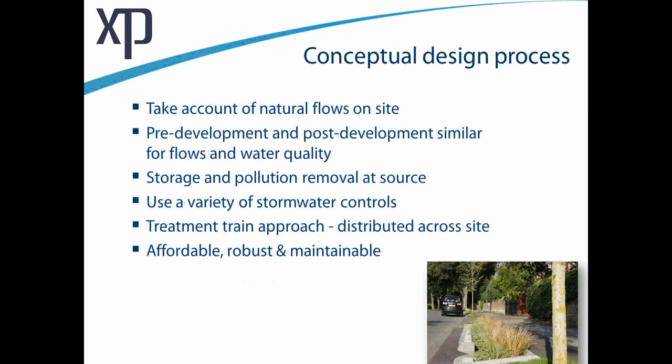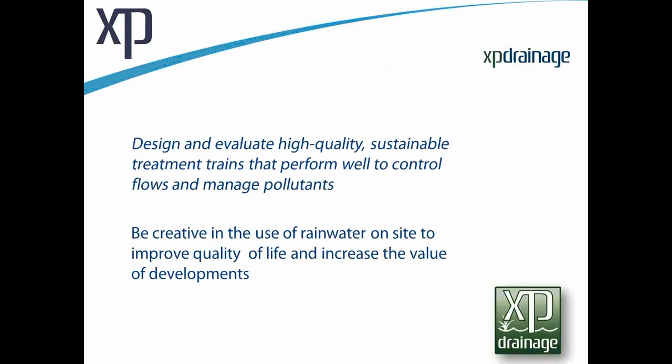Now, to do all this, it involves quite a change to the way that we design drainage. We want to now take account of the natural flows on site. Particularly important is to compare pre-development, post-development flows and water quality, and that's the main subject of today's webinar. But also today you'll see a bit of storage, pollution removal at source, using the treatment train approach so that we see the SUDs or WSUD distributed right across the site. And we always keep in mind that drainage design needs to be affordable, robust, maintainable. And we feel that you can use XP drainage to help make sure that's true.